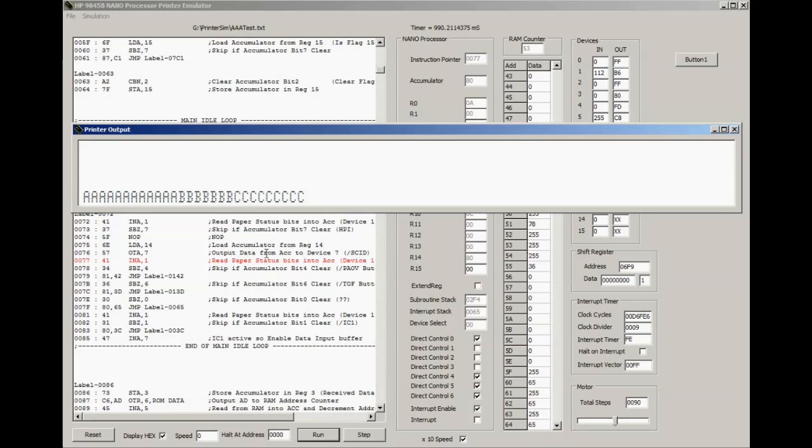And what I can do, of course, as you can probably guess I've been doing already, is go through the system, find out which part of the code does which operation, and then focus on that area with the logic analyzer, rather than trying to figure out this very complex and convoluted sequence that we would have to pick our way through if we didn't have this tool. And being able to just halt and run it gives us the best of both worlds.